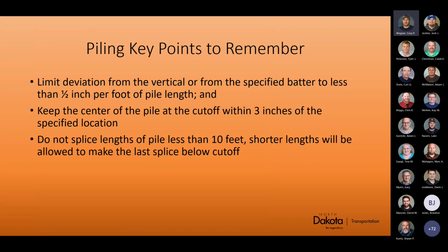Limit your deviation from vertical or your specified batter to less than 1/2 inch per foot of pile length, and keep the center of the pile at the cutoff within 3 inches of the specified location. If you get too far off, it can get into your rebar, and then they push your rebar, and that doesn't work because we need clearance on our rebar to the edge of the concrete. So those are things to watch, and it's amazing the things a pile will do as you're driving. They'll twist, they'll angle, they'll do all kinds of things.